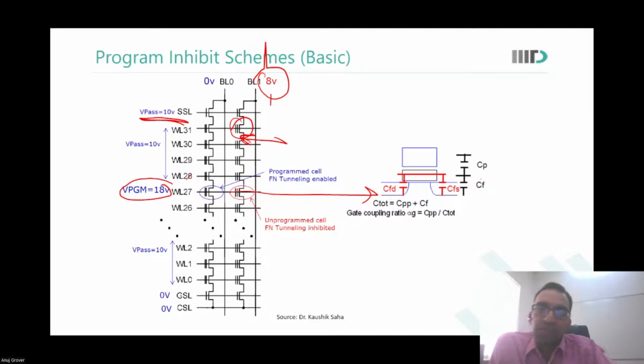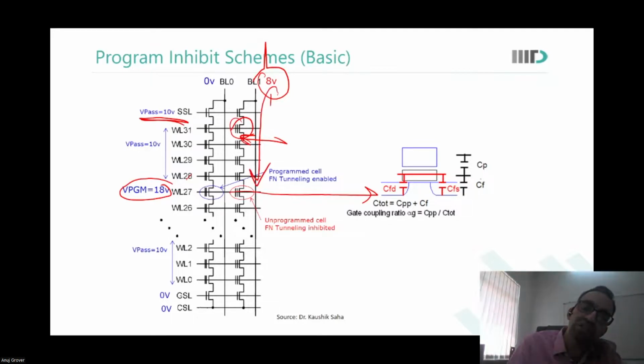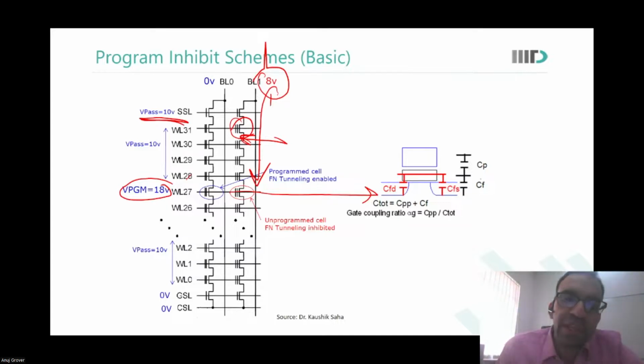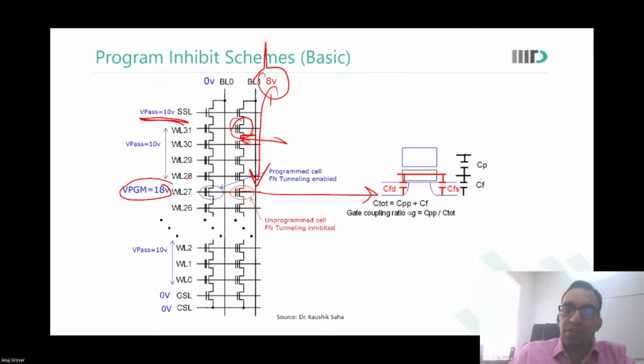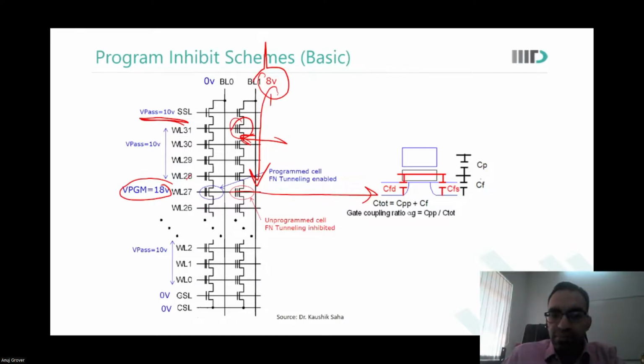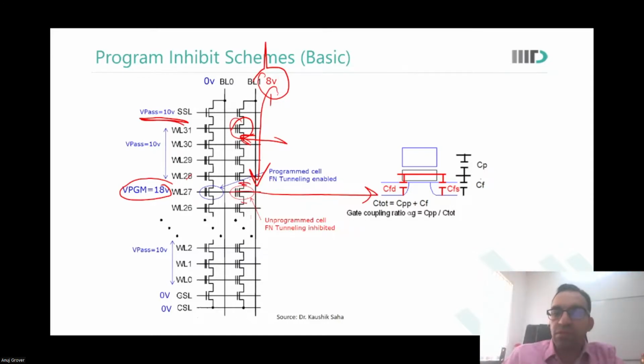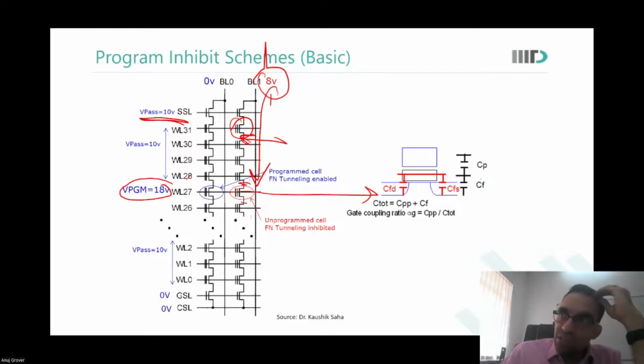8 only. 8 volts. So this 8 volts will pass to this last device. Now, when the 8 volts is there on its source and drain, you want to apply HCI, but now you cannot apply HCI. Why? Because 8 volts has got transmitted all the way over here, and therefore the kinetic energy or the inversion layer that is formed will not have that kind of thing happening. Is that okay? Yes, sir.